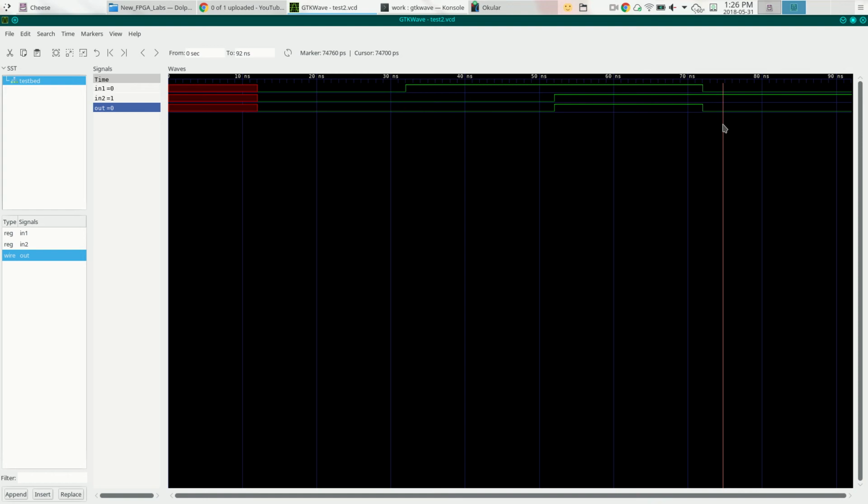Yeah? Is Verilog susceptible to glitches? Propagation delay? Yes. And we can actually enforce propagation delays. We can put in deliberate propagation delays to see what happens. So if we know that one thing has a certain delay and another thing has another, we can actually say, set the output equal to this after 2 nanoseconds. And we can generate timing diagrams that will actually reveal glitches to us.